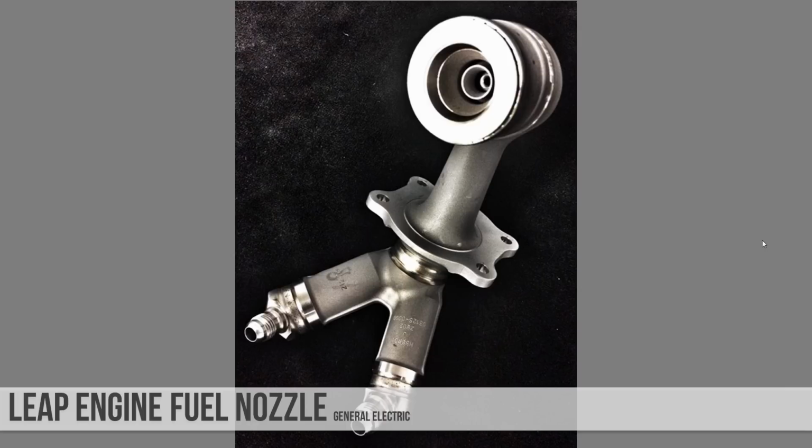So this is 2/3 lighter than the metal equivalent, the old design, and it can actually operate at temperatures 20% higher than the old design as well. And so it's up at temperatures where most alloys grow soft or become soft, and this is performing a lot better in many regards. Some of that is a design capability, but some of it is a material capability that, again, we have options available to us on the metal printing side. We don't have to deal with the difficulty of machining these metals or welding these metals.